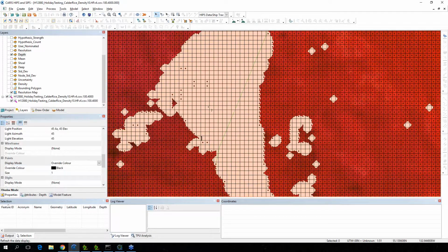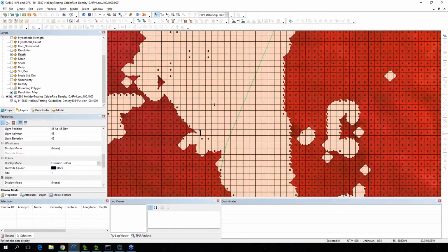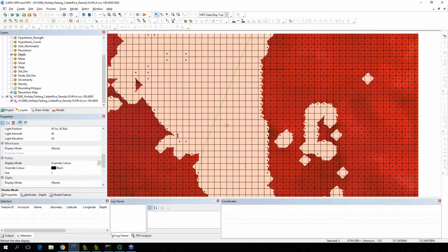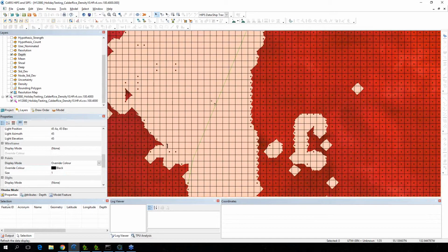So you could see here, Holiday Finder flagged this with the 1. So what it's actually doing, let's see, the depth here is 4.2 meters. This is a complete coverage survey. So I think the requirement is that the gap, in order to be a holiday, has to be 3 meters by 3 meters, right? If the coarsest allowable grid resolution is 1 meter. So let's see what the resolution is here. I think the resolution is, okay, so it's a 0.2 meter grid here.